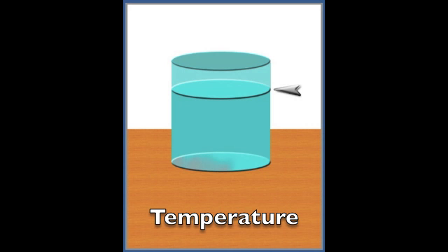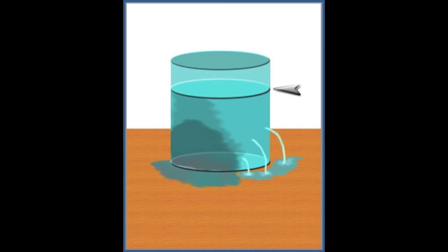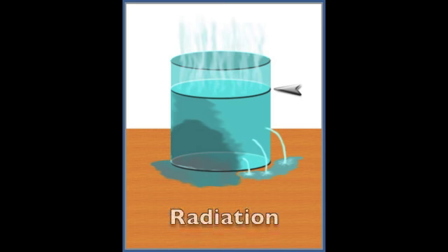A house loses heat in 3 ways: convection, conduction, and radiation. The leaks represent air leaks in the home, or convection. The seepage through the side of the tank represents BTUs passing through the building shell, or conduction. Evaporation out of the tank represents radiant heat losses.